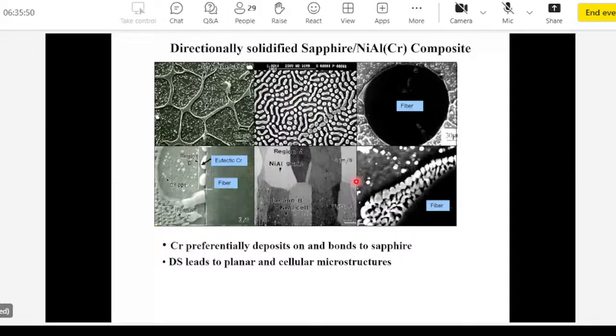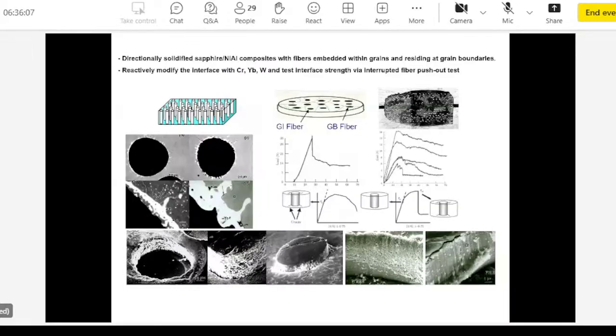This is again just the bond strength situation. You can actually measure the bond strength between the fibers and the matrix using what is called a fiber push-out test. You cut out a very thin wafer from the composite, like a slice like this, maybe 100 or 200 micrometer thick, and then use a micro indenter and push it through the disc here, and record the stress versus strain diagram as the fiber slides out of the matrix.